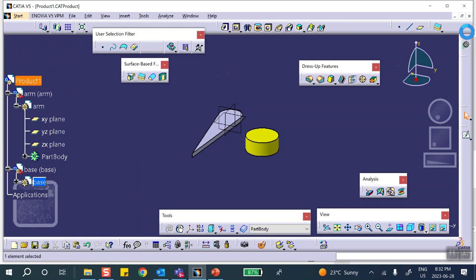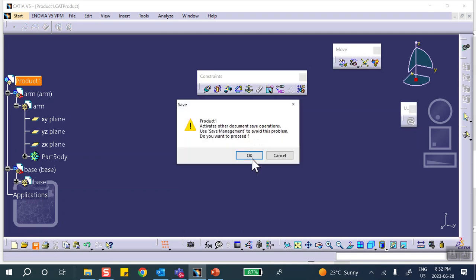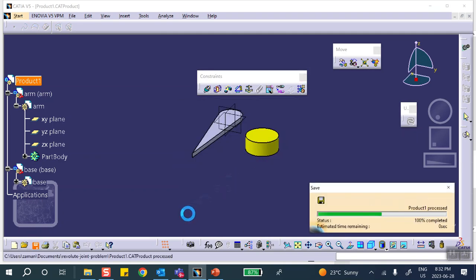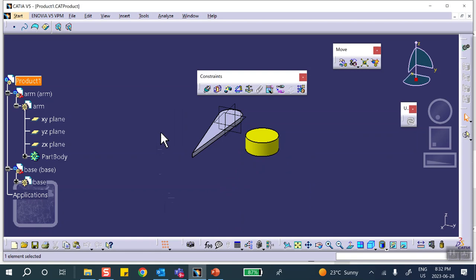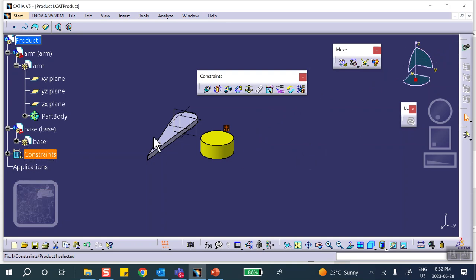Okay, all the way to the top, to go to the assembly design right there. See that? Double gears, and you click on the floppy. So these two parts are going to be saved in that same folder. Now we're going to assemble it. First, I'm going to anchor this piece because this is the stationary part. So I'm going to anchor. Now remember, these are assembly constraints that we are putting there. They're not joints, but we're going to use the magic wand later on to convert these assembly constraints into appropriate joints.